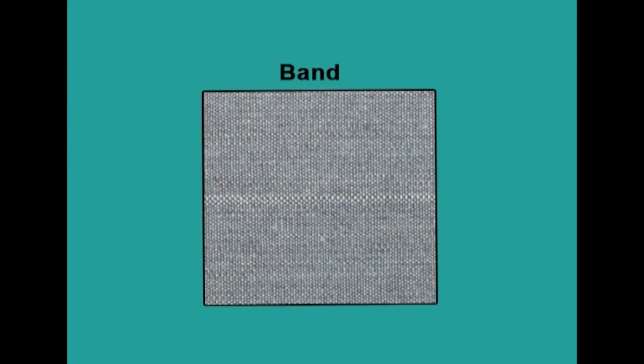And another defect is the band. It is a widthwise region of the fabric that extends across the full width and is different from the rest of the fabric. It may or may not run parallel with the courses and may or may not have clearly defined edges, as defined by the Bureau of Indian Standards. This is also considered as maybe a major or sometimes a minor defect.